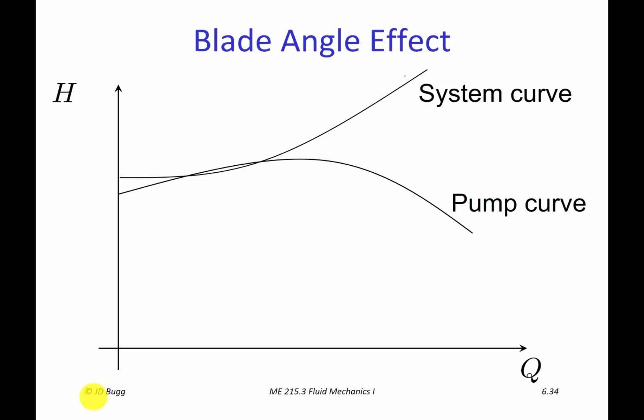One problem that we have when we have a positive pump curve like this, and this example illustrates that, is: is the operating point here, or is the operating point here? What this is telling us graphically is that if we take a look at the equations and equate our system curve to our pump curve, which is the typical way to find this operating point, we solve for where they intersect. Well, this actually has two intersections, and in fact it has a whole range of flows here where they're very, very close together.